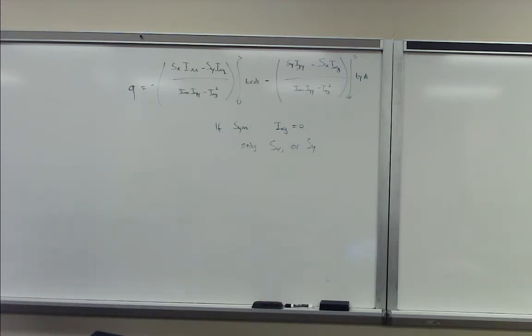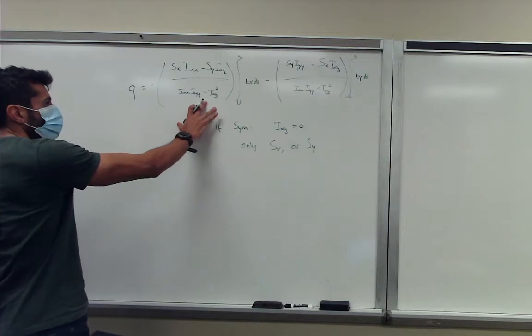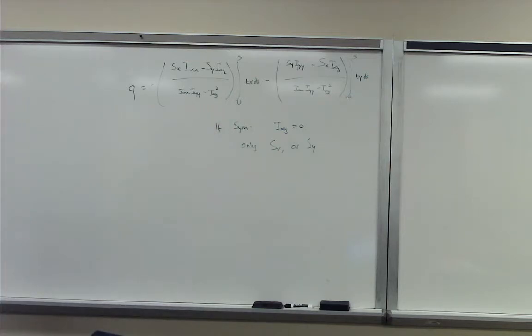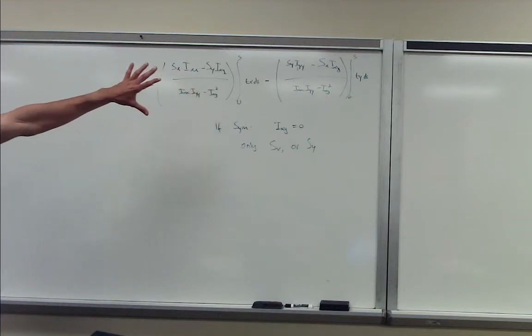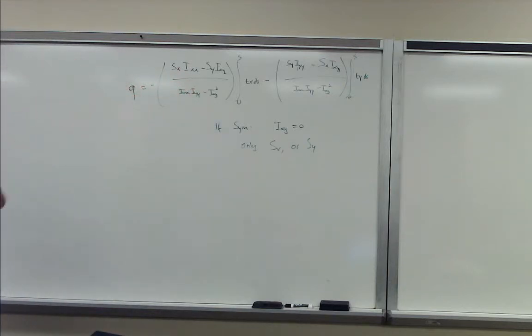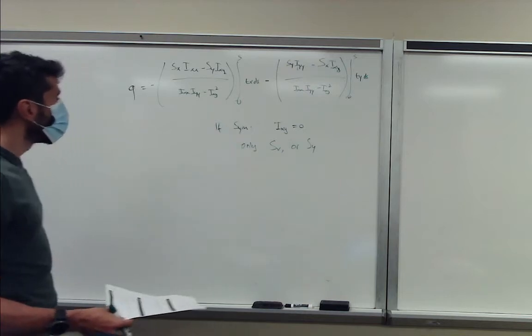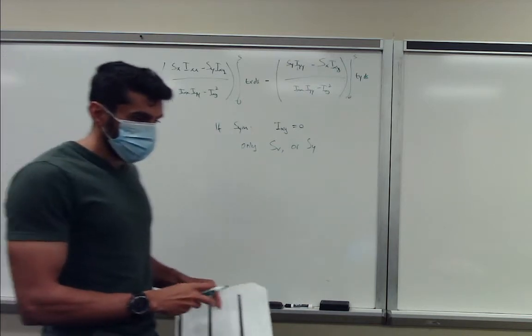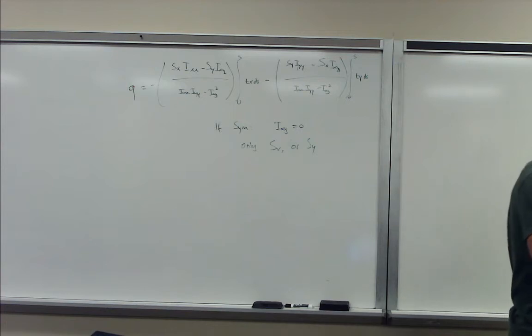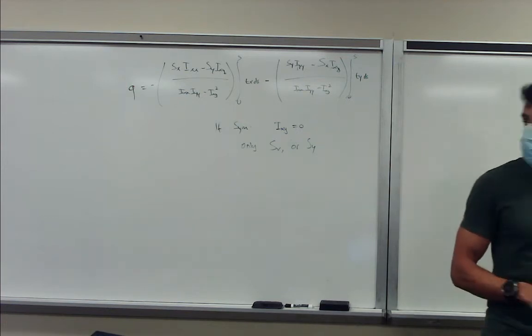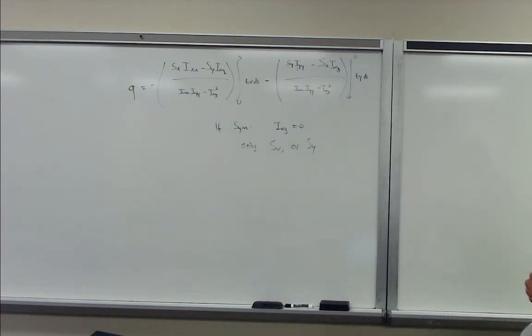So, what's the difficulty in this problem with shear flows? The difficulty does not come from your moments of inertia, because that's what we already did. That's your cross-sectional properties. The shear forces are given 9 out of 10 times. Sometimes a moment is given, and you have to derive a shear force out of that by just looking at what the arms are. So the difficulty from a shear flow problem is the integral formulation, or solving the integral part.